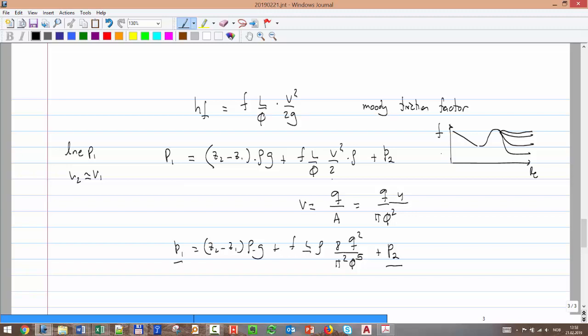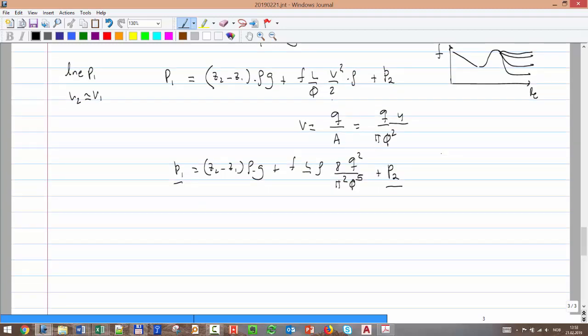Okay, now be aware here of something. This Q is the local rate. That means the local rate at pressure and temperature. Okay, it is not the same as the Q at standard conditions. Okay, Q oil, Q water, or Q liquid is not the same.